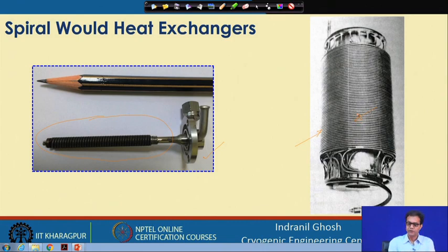I mean, it is a tube exchanger or tubular exchanger without any fin, whereas this particular spirally wound heat exchanger has an integral finned tube. So, this is spirally wound on a mandrel as well as having an integral fin on top of it. Typically this is called a JT cooler heat exchanger. This is a JT cooler and this is called a Joule-Thomson heat exchanger. So, we will not go into details of this one at this moment.